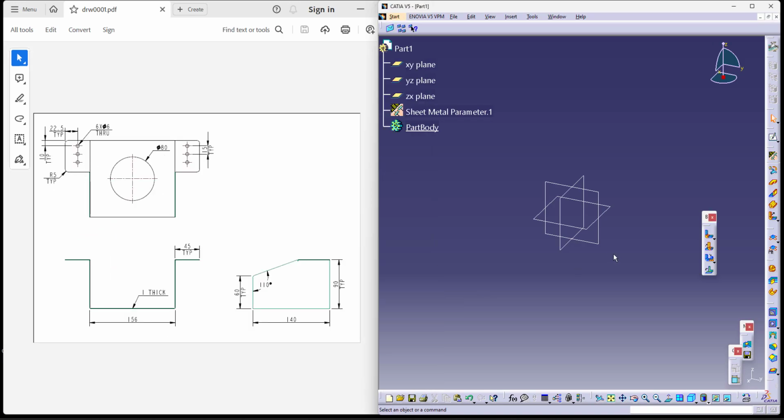To begin making this model, as usual, you can see that everything gets auto-highlighted. We can start with the base. Let's create a base by using either planar or extrusion. The better option is by using planar. So we can use the wall option to create the primary wall. There are two other options while creating this. The first one is when you want the thickness on one side or the opposite side. The second one is exactly in the middle. In this one, the thickness is only towards one side. So I'm keeping it at one side and starting my sketch.